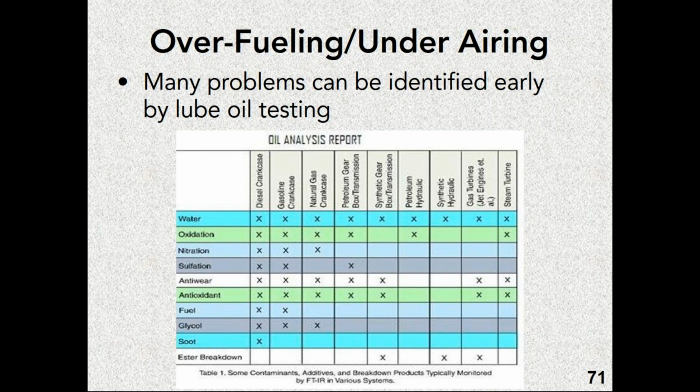Now, why is that important? Well, because if you're burning water or coolant, antifreeze, that's going to show up in the oil. Those leaks are going to show up in the oil. If you have too much wear in the turbocharger, the oil is lubricating the turbocharger, so it's going to wind up taking minor deposits from the metal that the turbocharger is made of, and that's going to show up in an oil analysis. So these oil analyses can give you an idea, sometimes up to 6 months in advance, of when something is ready to break in that engine. It'll certainly tell you when something is causing a problem with the emissions or the engine operation.